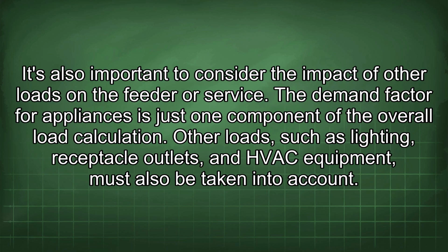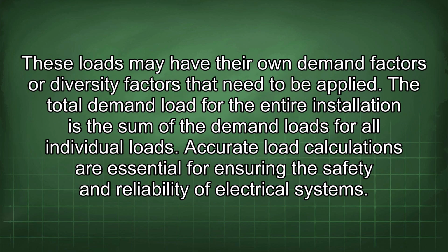It's also important to consider the impact of other loads on the feeder or service. The demand factor for appliances is just one component of the overall load calculation. Other loads, such as lighting, receptacle outlets, and HVAC equipment, must also be taken into account. These loads may have their own demand factors or diversity factors that need to be applied. The total demand load for the entire installation is the sum of the demand loads for all individual loads.